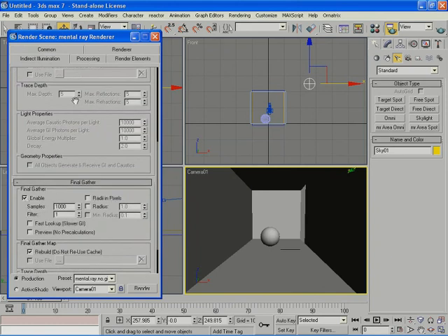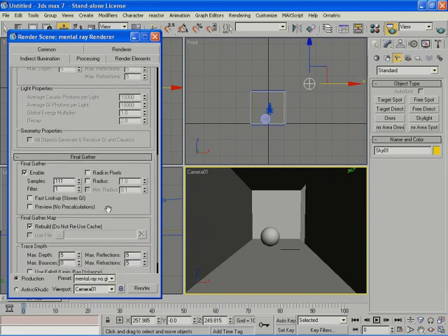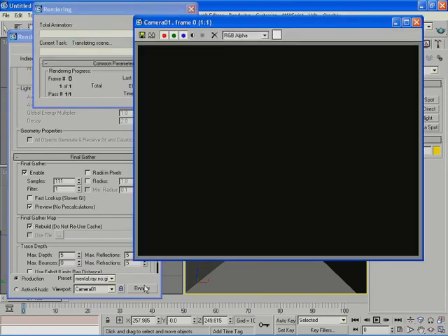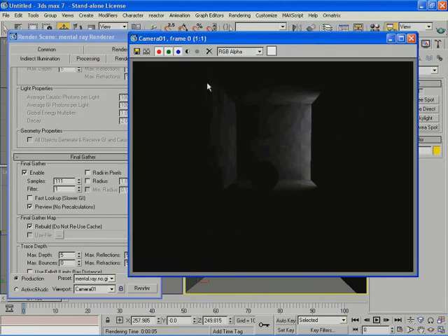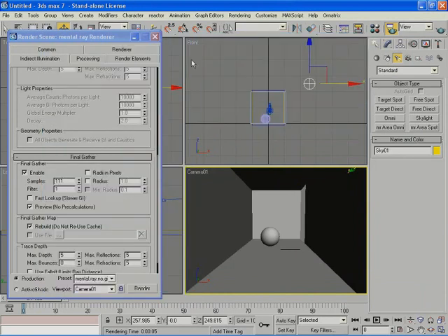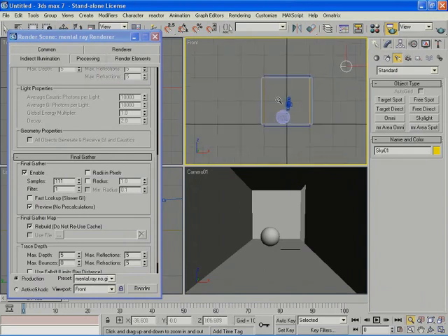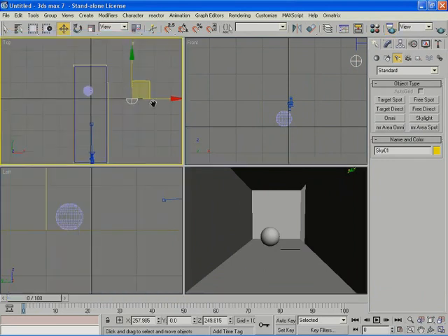So right off the bat, I see that I have the skylight coming in and filling up just the little portion of my entrance. I want the light to globally light the whole hallway with the brightest area from the opening. I'm going to change the background color and set it to pure white. And I want to start working on the brightness of the scene. So the first thing I will do is create an area light that will simulate skylight coming through the opening. Although I do have a skylight object or light here, I still need to create another area light that would be the light source from the opening that will enhance the lighting inside the scene.